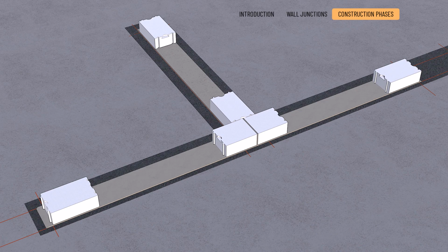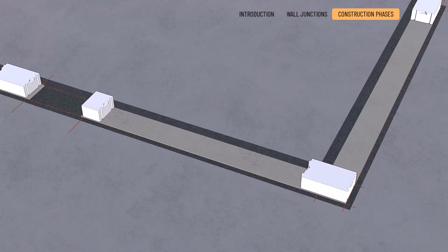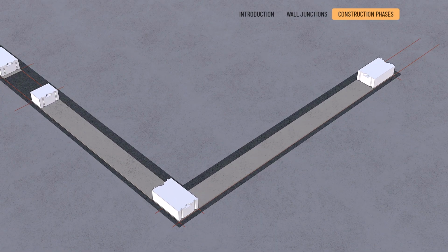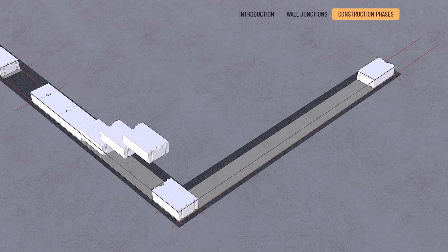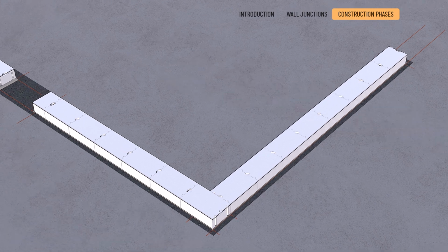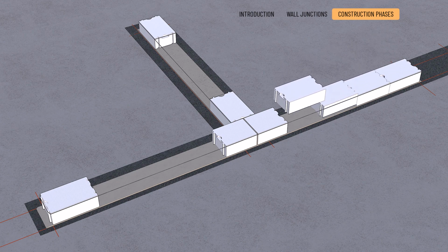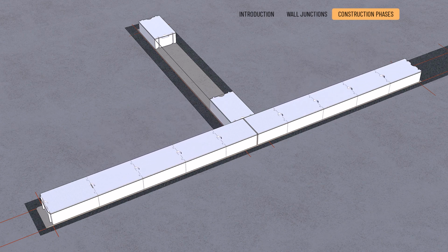The whole block of the adjoining wall butts into the main wall. Use a leveling bar and a rubber mallet for horizontal and vertical adjustments. 4. A masonry cord is stretched out between the already placed blocks, and the filler, stretcher masonry, is done here. The blocks will be laid along the original plan without any vertical mortar joints.